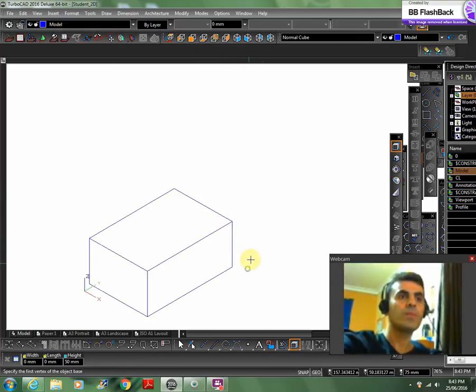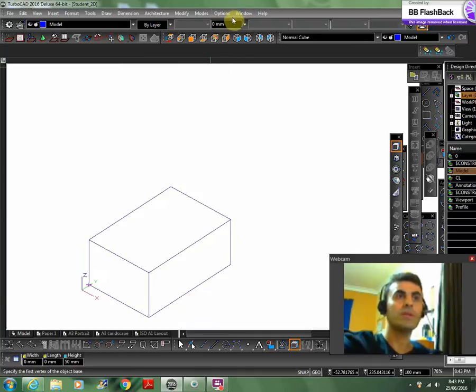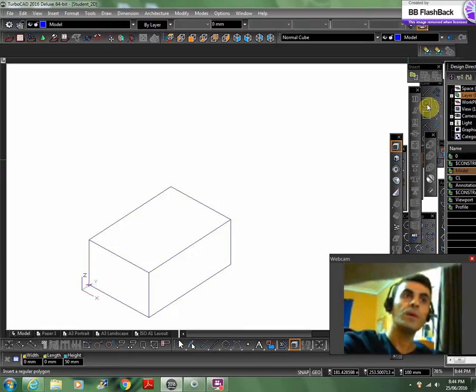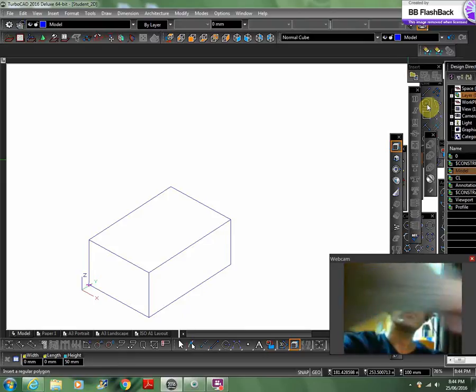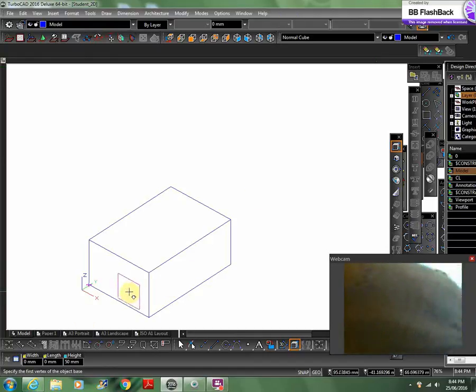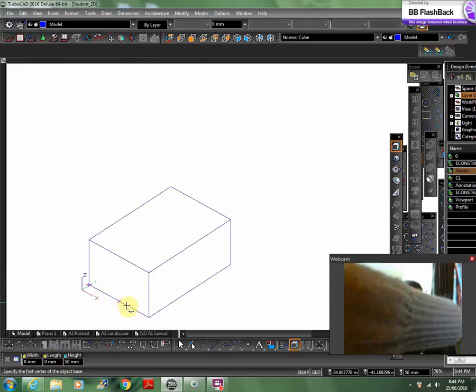What do you want to do? So now I want to draw the base of the prism. For that one I use polygon. Choose the polygon. Which plane do you want to use? You have to be on the right work plane. Now the work plane is here. Which one? Whenever bottom? Yes, okay.